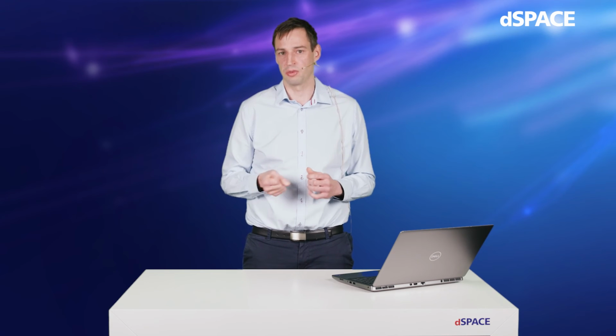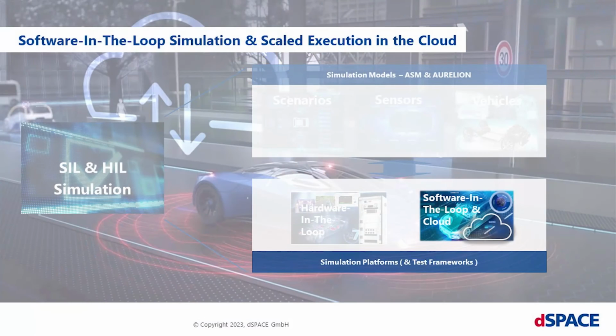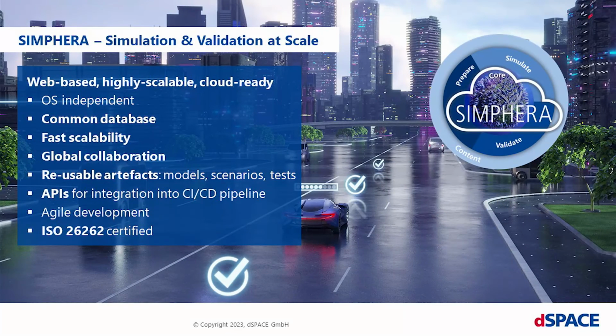So what we have seen now is how we have virtualized a recording of raw data using the labels from Understand AI, creating a replica scenario and having the direct, exact replication of the scenario in simulation. In the last minutes, we've only shown the simulation on a local desktop in our SIL simulator VEOS. But for verification and validation of ADAS/AD, massive and scaled SIL simulation is required. And this is done with SIMPHERA, our web-based, highly scalable, cloud-ready simulation framework.